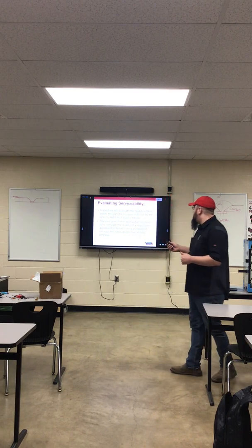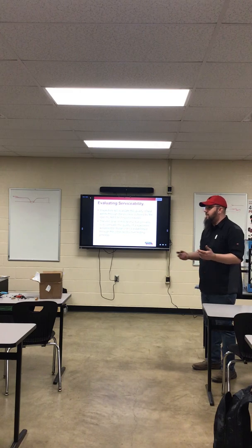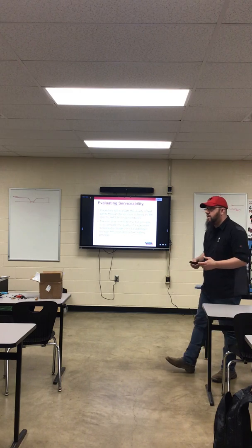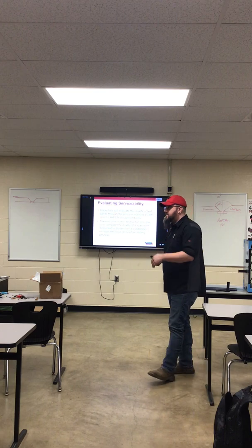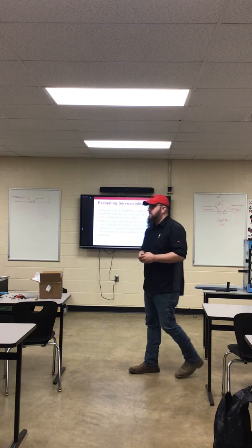Now, when we bend them, how do we bend them? Do we just pick an arbitrary direction to bend them, or are we testing specific parts of the weld? That specifies which ones: 3/8 is face and root bends, and 1 inch is side bends, right? Correct.